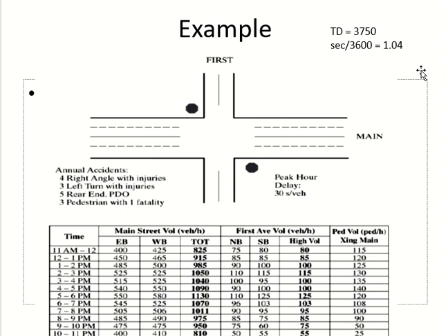We are only looking at crashes which can be corrected by a signal. You put a signal, these crashes will become low. Which of them? At least some of them, right? Which of them? Right angle maybe. Right angle, obviously. Signal will block one of the travels, right? Okay, what else? Left turn, obviously. And pedestrians. What about this one?